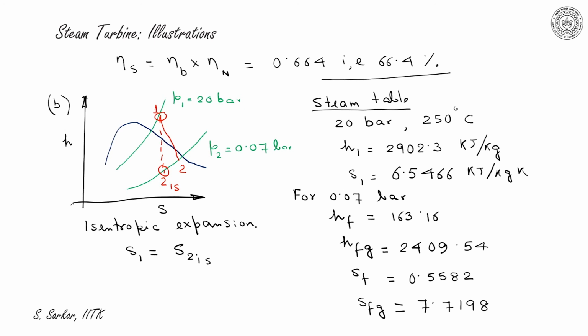Now considering the value of SF and SFG and also S1, one can imagine at point 2 there should be some wetness value or dryness fraction.